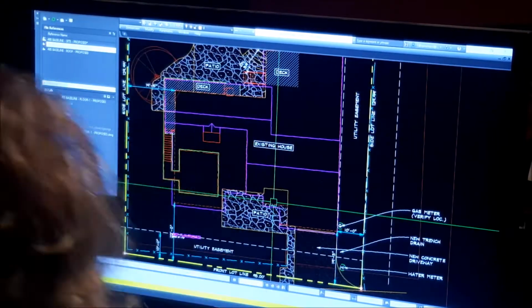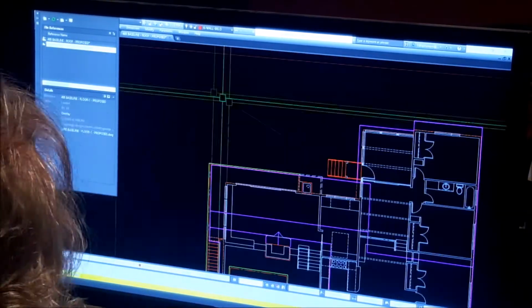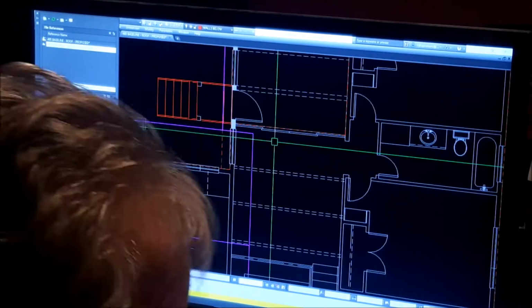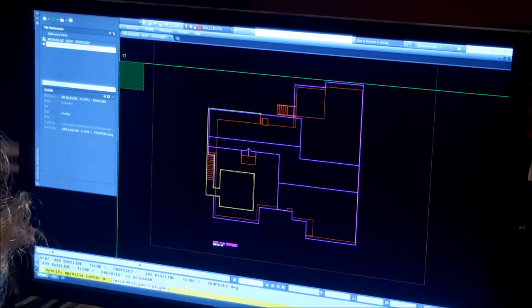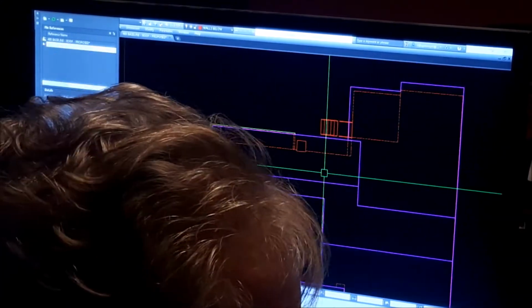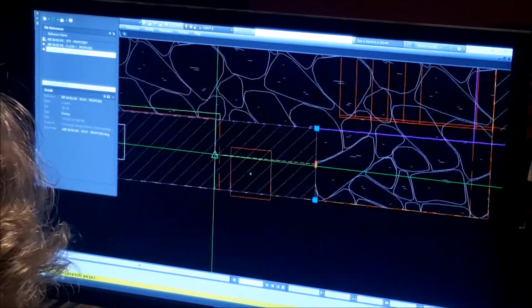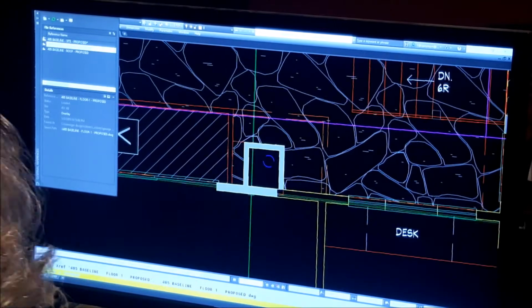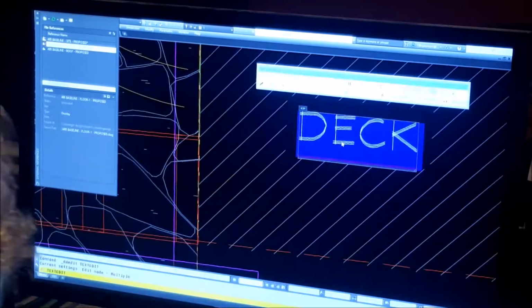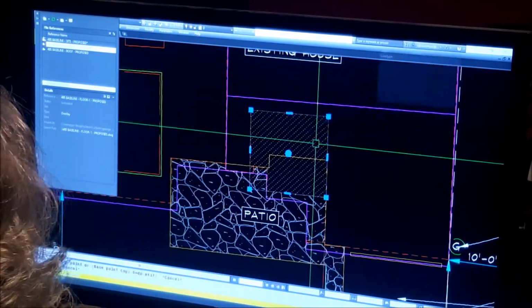What else is happening? This is an XREF. I'm going over into the, I think, roof plan and updating a few items on the roof plan that he had changed. Then when I close it, it'll bring me back into the site plan that I'm working on. I'll X-reference a couple things there. I wanted to name that screen porch.